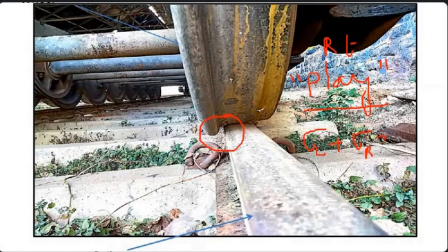So that means the left play plus right play, in the case of coaching or wagon stock, is equal to 19 mm. How this 19 mm came, I will explain to you. So I am repeating once again. The left side play plus right side play is equal to 19 mm. Sir, this 19 mm, both together it is, not one side.